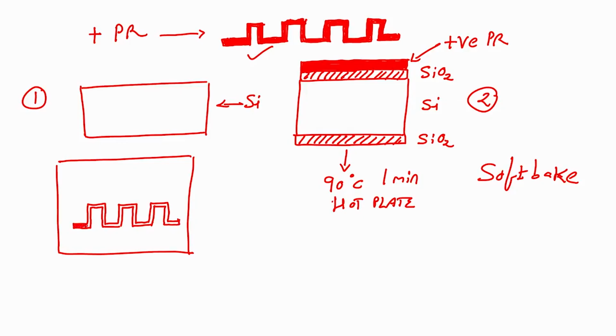So, you have a mask with this particular pattern, and we have discussed that this mask where the pattern is dark, and the field is bright, is called a bright field mask, right.